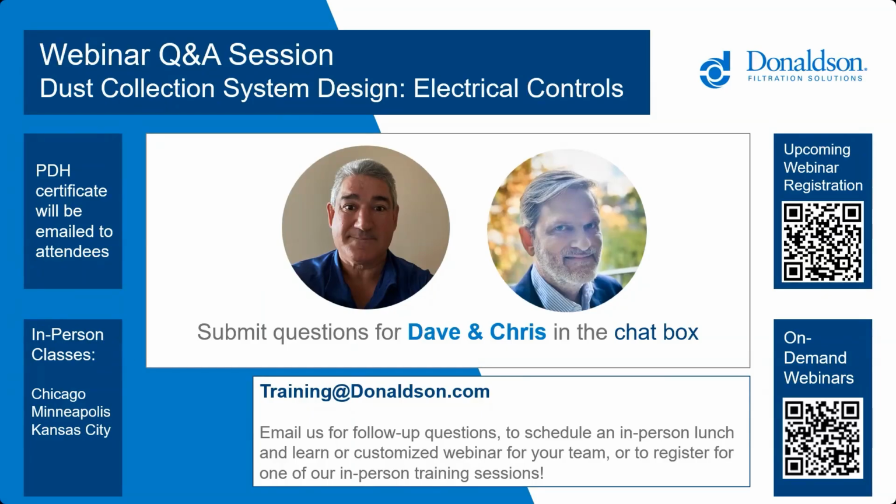All right. Would you typically specify a dust collector with a VFD? I would say on my school jobs in Wisconsin, 90 to 95% of them have VFDs on them now. The ones I've sold in the last 3 to 5 years all have VFDs because they want to maintain constant airflow. They want a system that's rated at 5,000 CFM to maintain 5,000 CFM, so the VFD ramps up and ramps down to do it. It's an added cost. There is a reward you get from Focus on Energy for VFDs, so you can get some money back. But I see most of them in my systems. VFDs are very prevalent in the school jobs that I've sold recently, for sure.